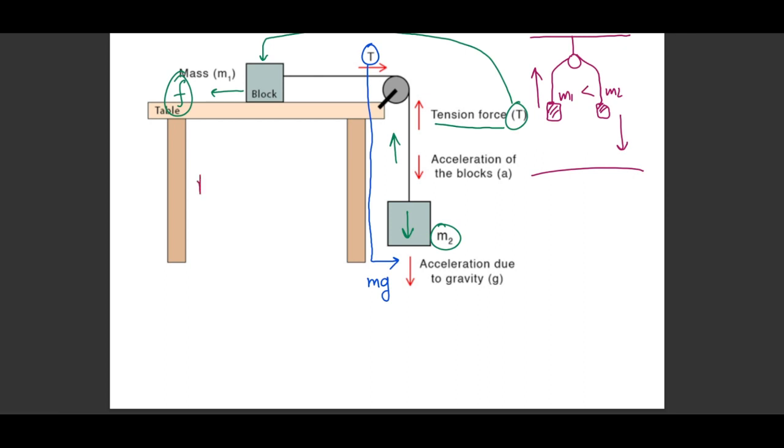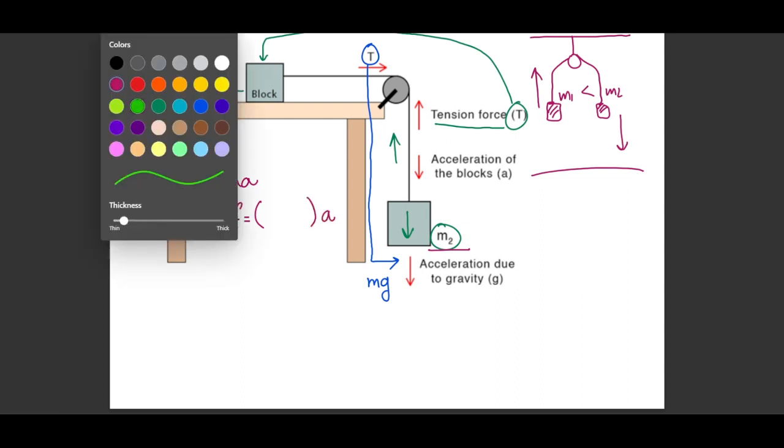So we're going to apply F equals ma. Now let's look at what factors are trying to move the system. We understand that m2 is trying to move it, so the weight m2g will be the pulling force, minus the friction that is trying to stop this object from moving, which is coming from the other object, right? So this will come over here as F equals, now mass is interesting, we will discuss that later, and acceleration is what we're trying to find out, so it stays as it is.